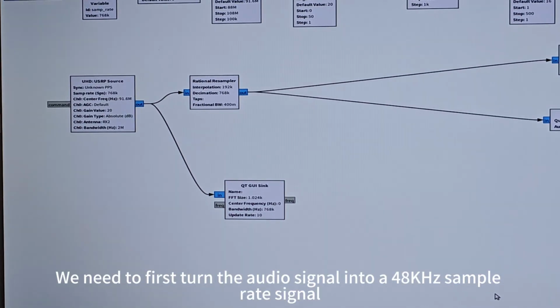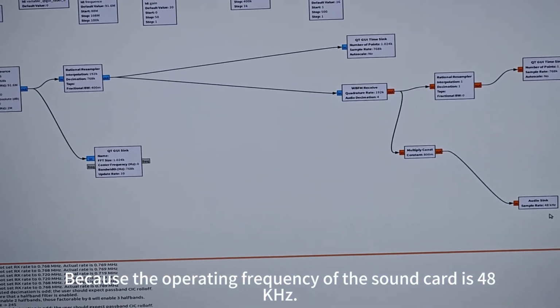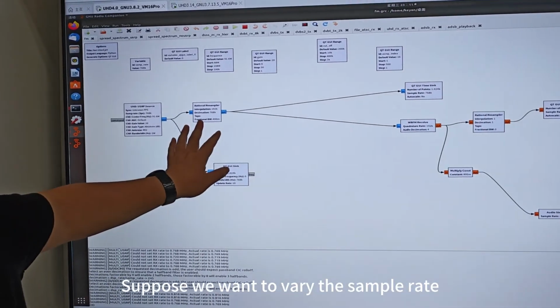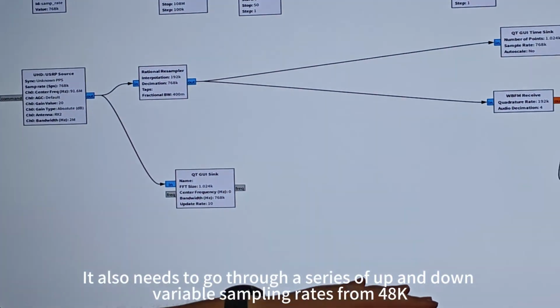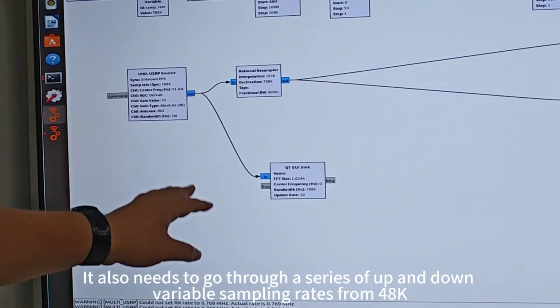What about after getting it? We need to first turn the signal into a 48 kHz sample rate audio signal. Because the operating frequency of the sound card is 48 kHz, we have to go through a series of processing to change the sample rate. Because the sample rate is currently set to 768,000, it needs to go through a series of up and down sampling to reach 48,000.